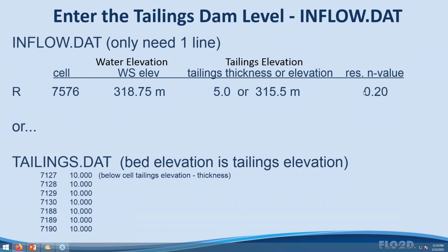Because you've discretized the surface into finite grid elements, the minimum elevation difference between the water surface elevations might be a thousandth of a foot, but that's a fairly steep slope when you're only dealing with maybe 10 feet or 20 feet or something like that. So the idea here is apply this and you'll get reasonable velocities in your reservoir as the reservoir drains. This is more necessary for filling the reservoir than it is draining the reservoir, but it still works.